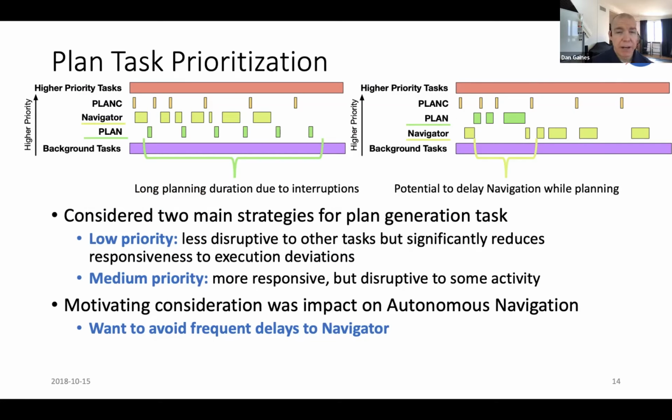And the benefit here, one of the advantages we have with the Mars 2020 autonomous navigation system beyond MER and MSL is that we've made it such that the navigator does what's called thinking while driving. While wheels are turning, we're actually building hazard maps and planning routes. As long as the navigator can keep up, we never need to stop wheels from turning. And we can drive much faster doing autonomous navigation than previous rovers could because of that. So by having the navigator above the planner, we always give the navigator the best chance of keeping up so we don't slow down our drives.